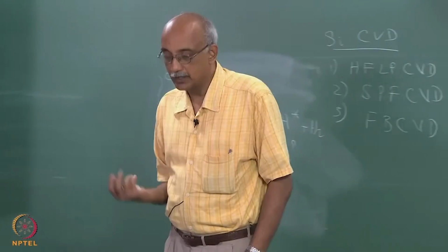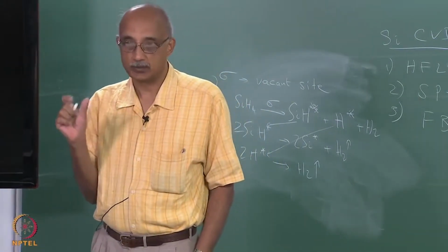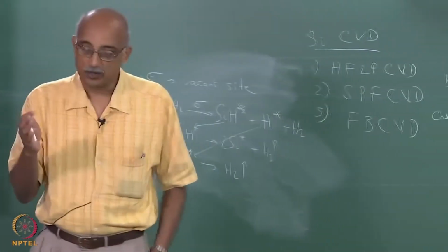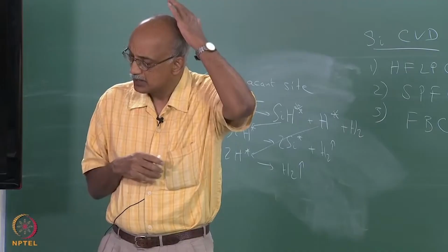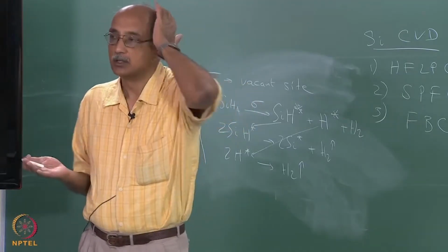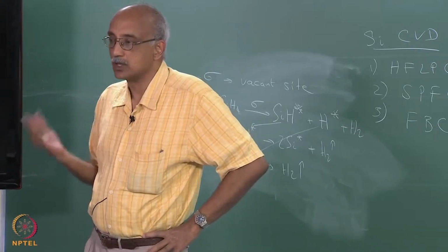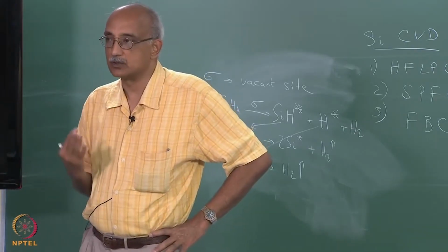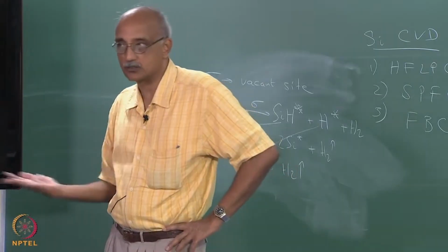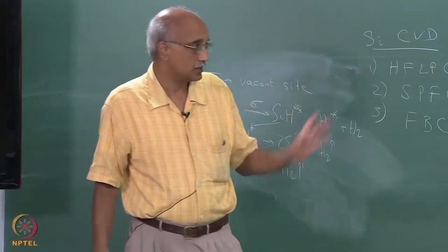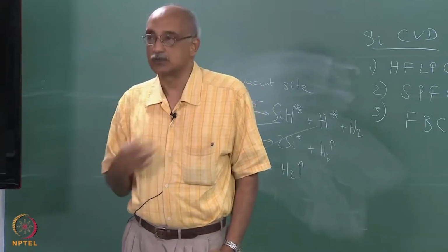It also will depend to some extent on the viscosity of the fluid between them, which can also affect how close the particles or the molecules can approach each other. It really depends on the intermolecular forces as well. What are the van der Waals forces between the molecules, what are the electrophoretic forces between the molecules, what are the ionic forces between the molecules, what are the surface tension forces, what are the viscous forces. So, this cohesion coefficient actually depends on all of these interactions.